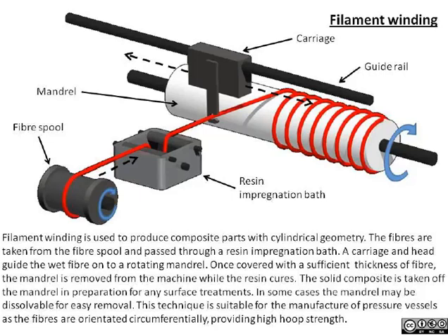Kind of going to the other end, we can process in tension, especially if we have a continuous fiber. So we can unwind maybe a slightly pre-impregnated continuous fiber from a spool. This is very advantageous for textile fibers like Kevlar, HMPE that are quite flexible in their non-impregnated state. We will add more matrix resin as needed before winding onto a mandrel, and then, of course, finishing the cure either in an oven or, if possible, at room temperature.